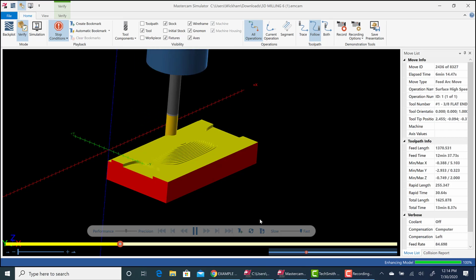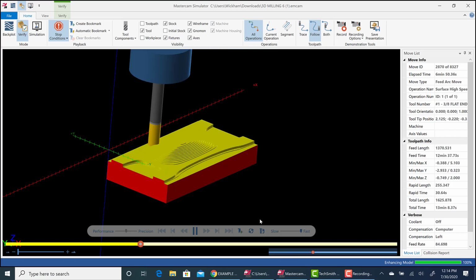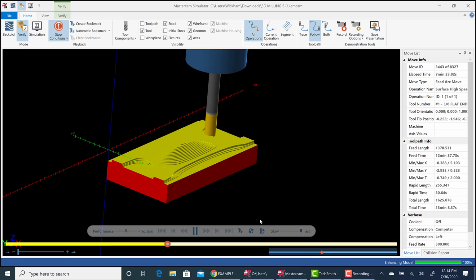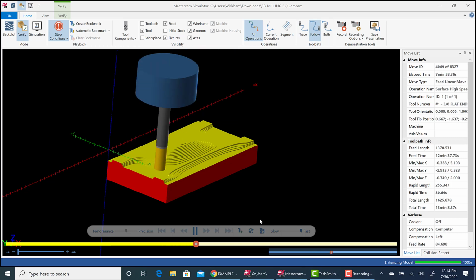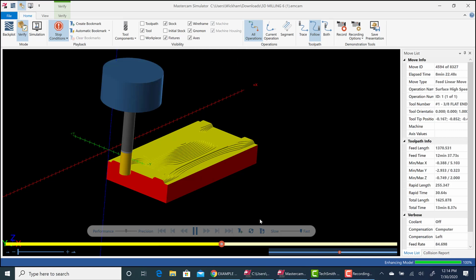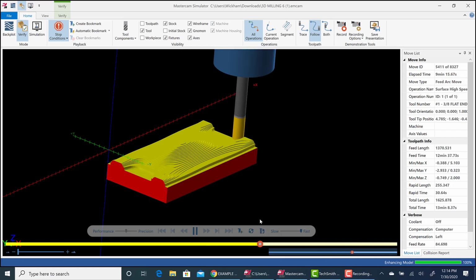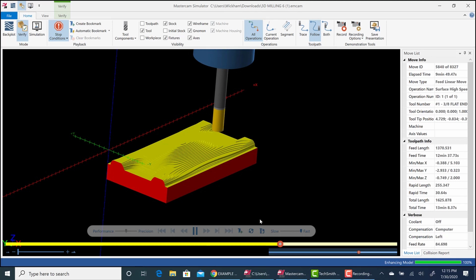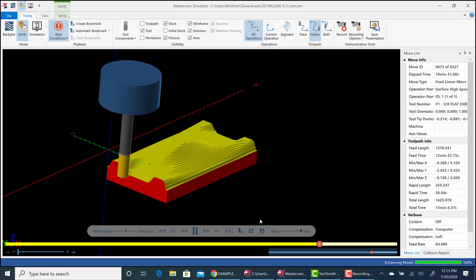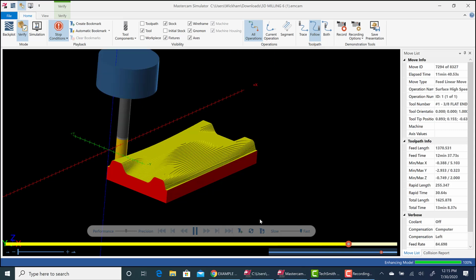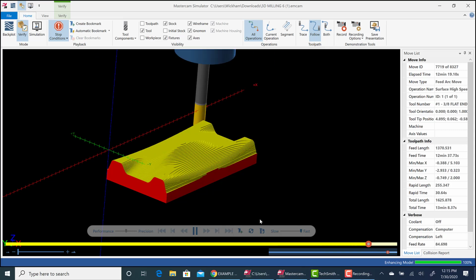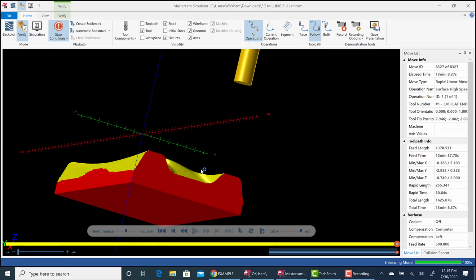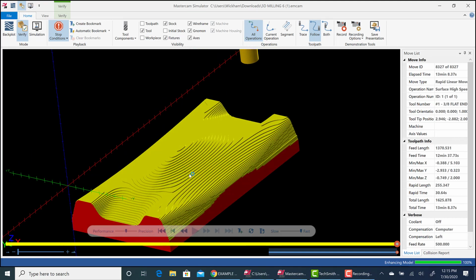Like I said before, you don't really have to work top down. This is not really a dynamic path, although we're sort of using some of the tools with it. I prefer working like this. I think it's smoother, especially if you're doing just one part. It may not be the most efficient for the tool itself, but it's only 13 minutes, and we could tweak it from there. We could probably increase some step overs and make it pretty fast, but there are two schools of thought on that. As you'll see, we have nice even stairs, and that's really what I'm after. Okay, that looks pretty good.